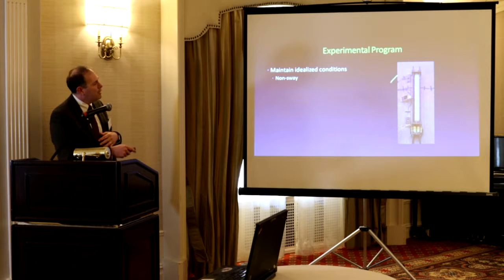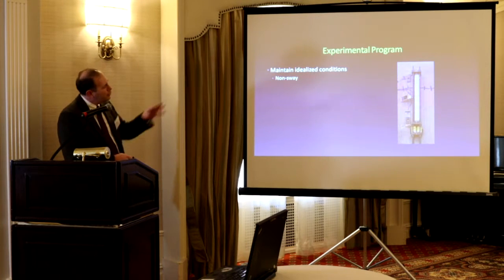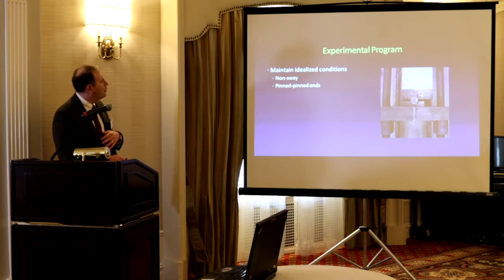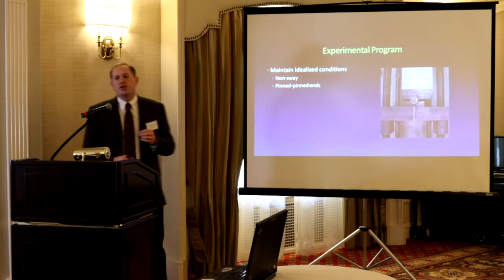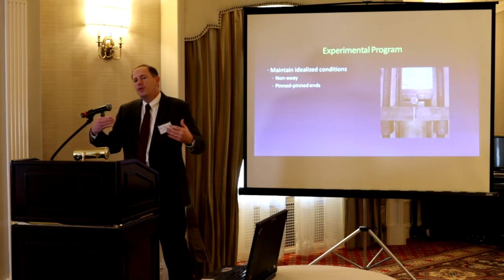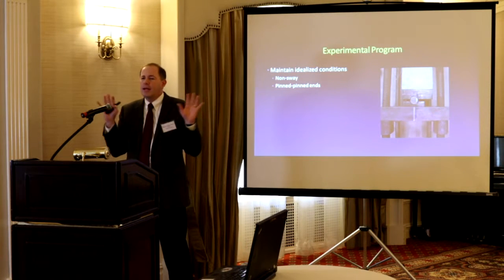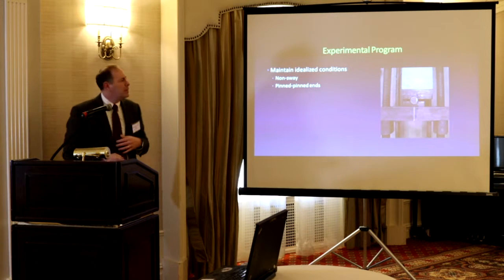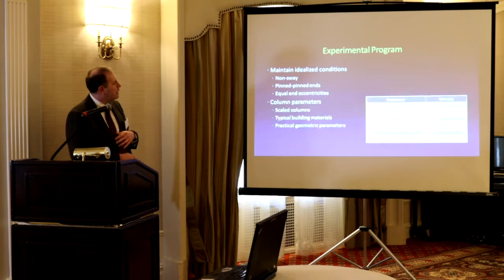We looked at non-sway. This is a picture of the frame with the loading jacks here that we load, and then we lock the nuts down here to sustain load. We measured the displacement at the mid-span. So it's a fairly simple loading. We have pin ends. So we can put exactly the eccentricity. And for this, we wanted to compare to actual analysis. So we made the two ends the same eccentricity. We know the C sub m that's in the code works well. That's been validated. We wanted to understand the second order. And then we had, as I just mentioned, that equal eccentricity at the end.